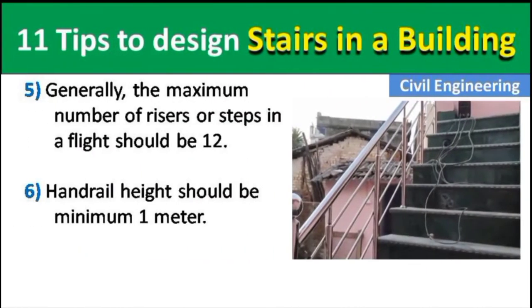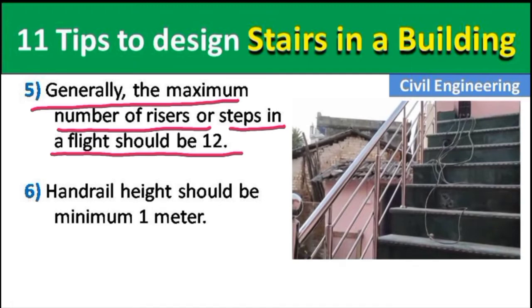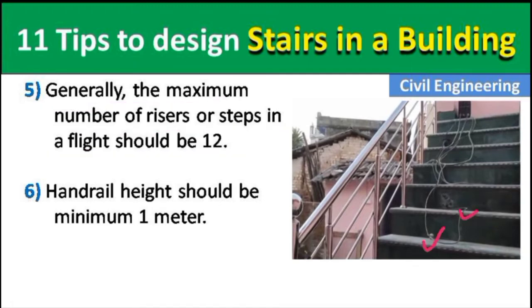Okay, now point number 5 is, generally, the maximum number of risers or steps in a flight should be how much? 12. Okay, so steps is 1 step, 2 step, 3 step, 4 step, like this, and this should not be more than 12 in number in one flight.